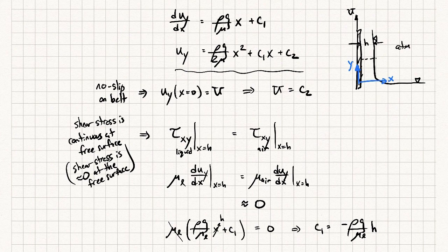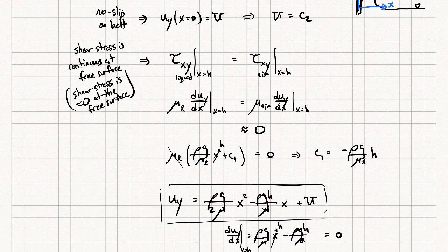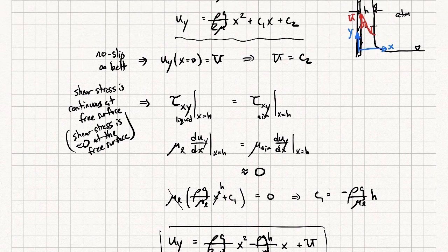Let me put this in a different color, put it in red. So it's moving upward at a velocity U right at the surface, but it may actually move downward at the free surface. We don't really know exactly. So the velocity profile may look something like that, for example, where that's kind of a parabolic shape. It all depends on the relative magnitudes of these various quantities in the expression here. But what we want to know is, what is the volumetric flow rate headed upward here?